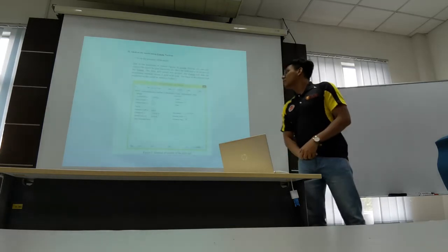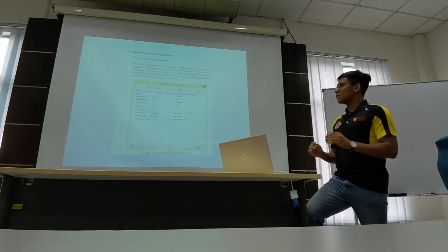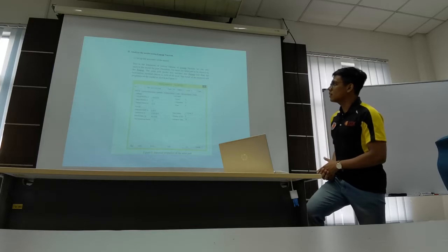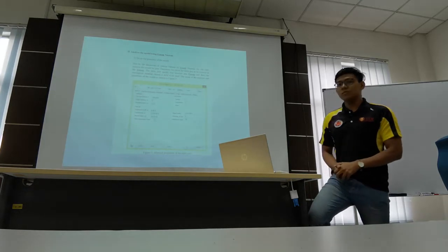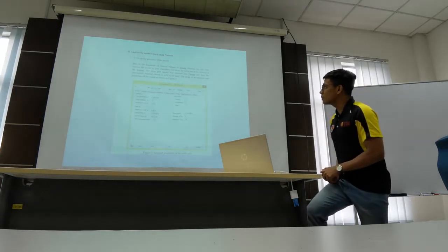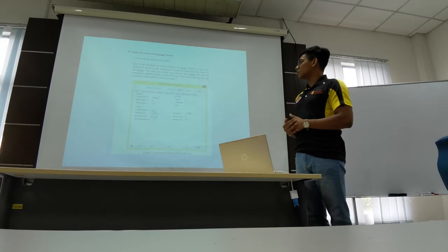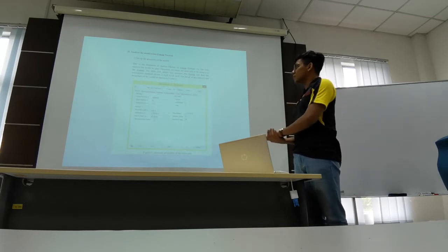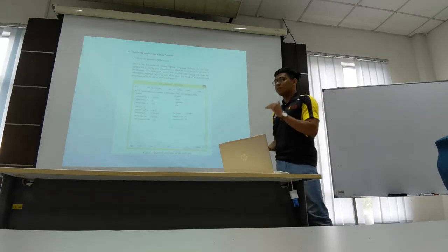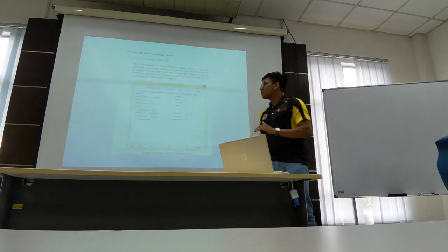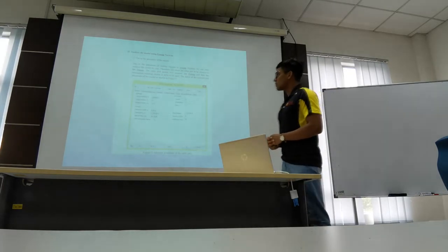Okay, and then the second step is, after we finish the design, we import it to FEMAP NASTRAN. The first process is to set up the geometry model, and just like what Farhan said, the material selection in FEMAP NASTRAN is limited because it only has steel but not plastic material. So for our scope, we use AISI 4130 steel, and these are the details.